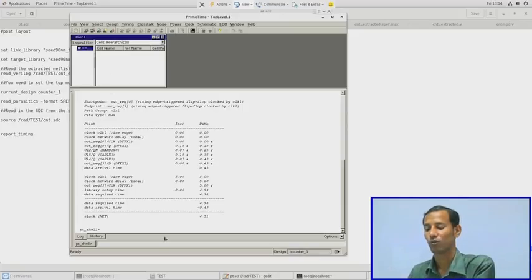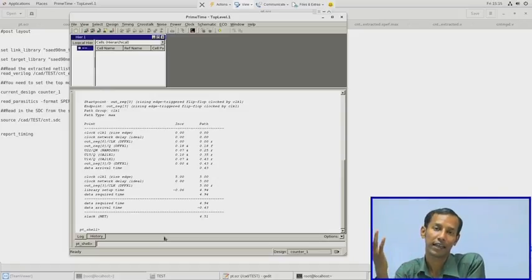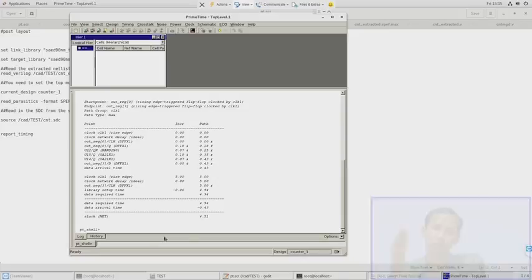Okay, so that means as the slack is too high, again you have to start with Design Vision, you have to change the clock period, again you have to follow this whole step, and again come back to IC Compiler, check that, extract all this information, delay information, parasitic information, and the corresponding Verilog file, and again come back. So manually, graphically doing this process iteratively is very hectic.